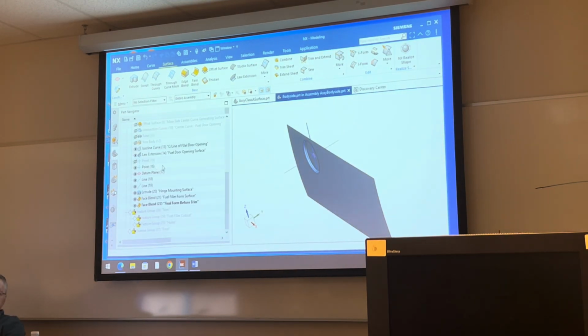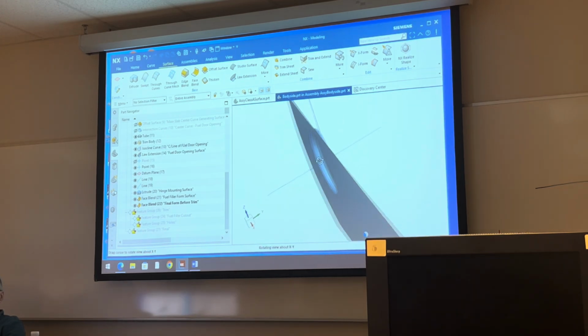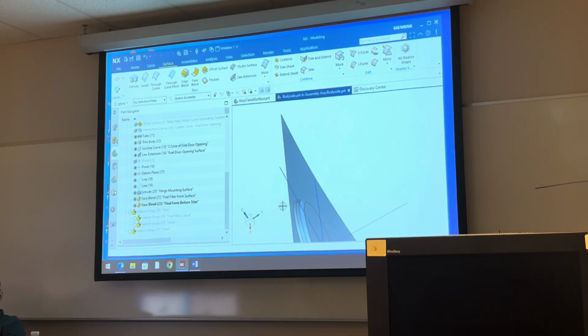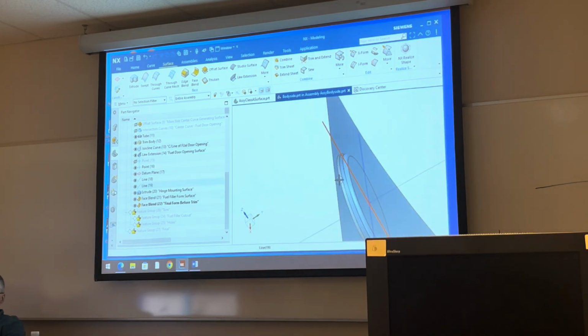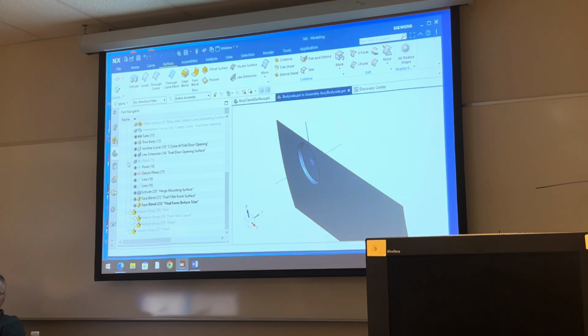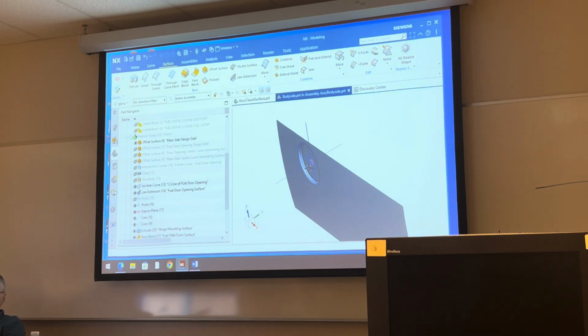And not that this is something you need to do, but if I show the tube, trim body, show that. Again, it should be sitting right there. It's nested right where the fillet is. So we kind of worked backwards. We started with something that represented the material thickness, knowing the fillet had to be 3 times the material thickness.